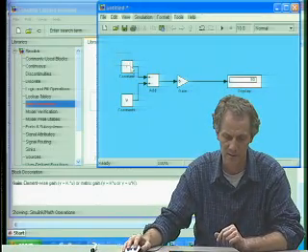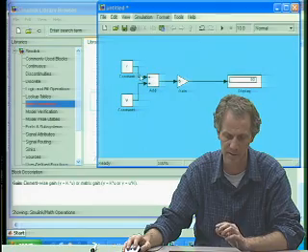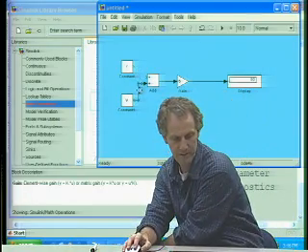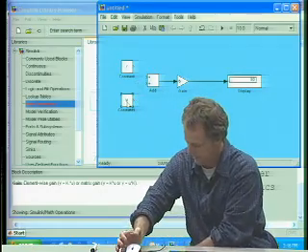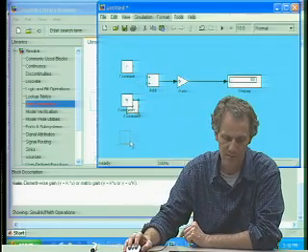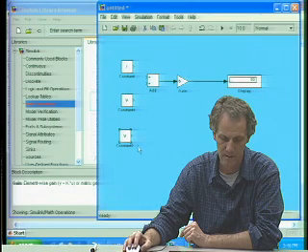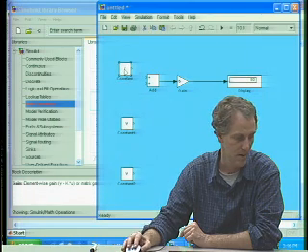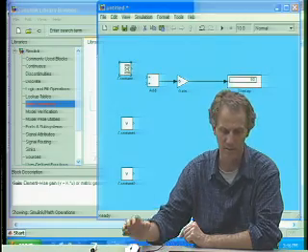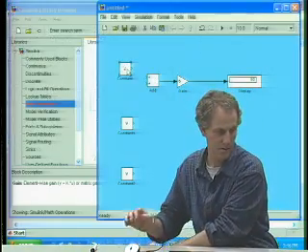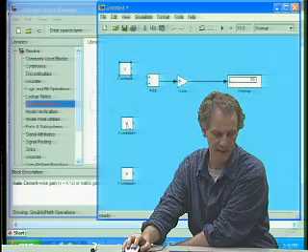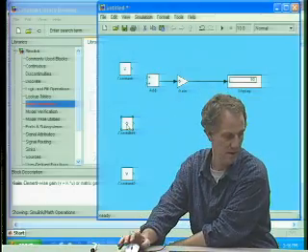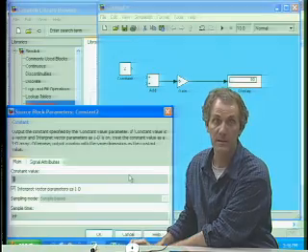I'm going to actually use some of these same tools. I needed the constant blocks. I'll need 3 of those. So let me put those out here. The constants were 2, and then negative 5 in the second equation, and 3 in the third equation.